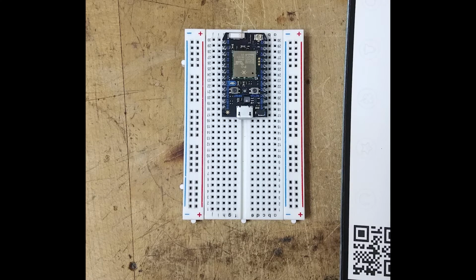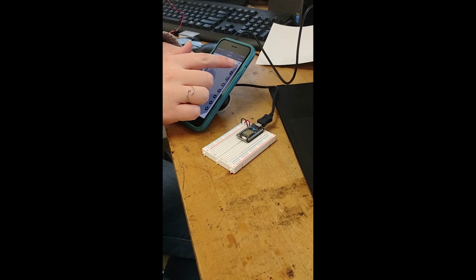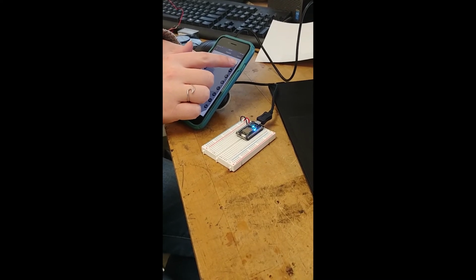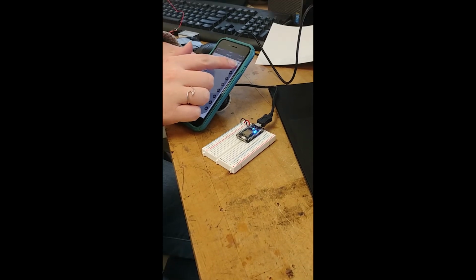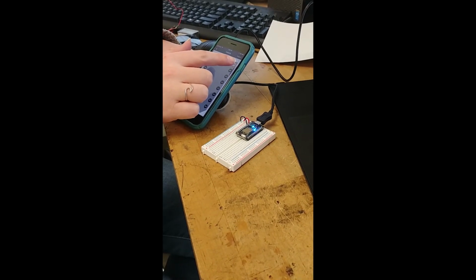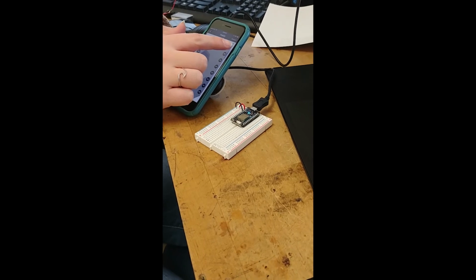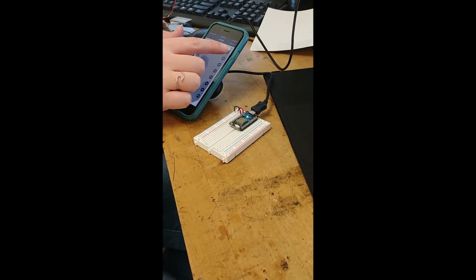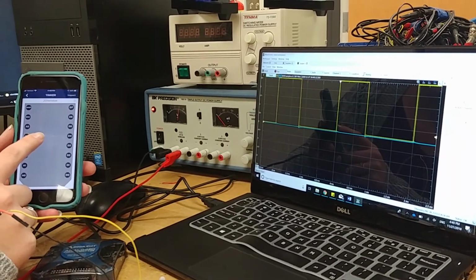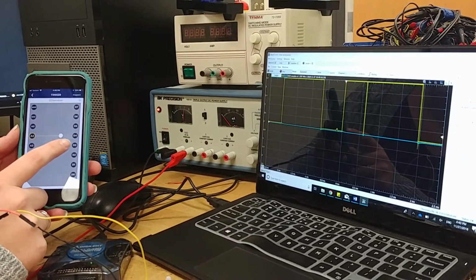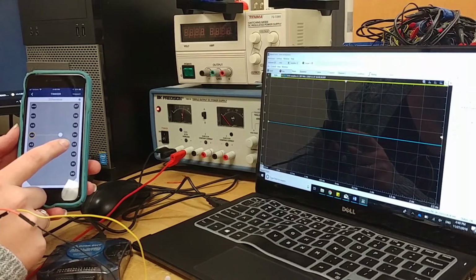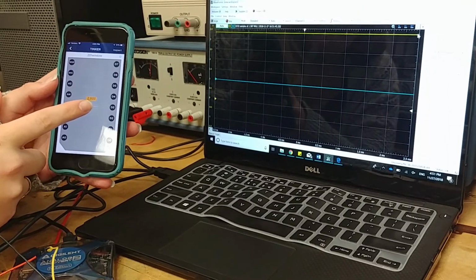First, we set up the Photon using the app on the phone and confirmed it was connected to the internet using the Tinker program that comes already on it, which allows you to turn on and off the onboard LED. Of all of the analog outputs, to determine which one we wanted to use, we decided on the one that changed voltage rather than the duty cycle.